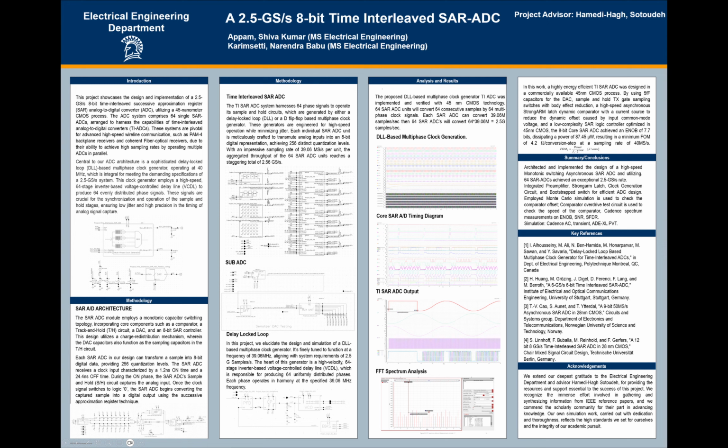In the conclusion, we built most of the circuits: the preamplifier, StrongARM latch, clock generation circuit, and bootstrapped switches for the core ADCs. We did Monte Carlo simulations to check the comparator offset. We found proper ENOB, SNR, and SFDR, and ran Cadence transient simulations. At the end we got the expected output, as you can see in the diagram.